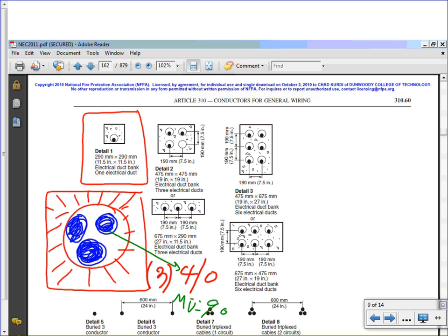Mistake number 1. We're dealing with medium voltage cables here. THW is gone. Your insulation is called MV90, medium voltage 90. Brand new insulation for medium voltage. I don't blame you for saying THW, but you go to the high voltage THW, open the window from the 3rd floor and throw THW out the window. THW doesn't work with higher voltage. So it would be MV for medium voltage, 90 for the temperature rating of the insulation.